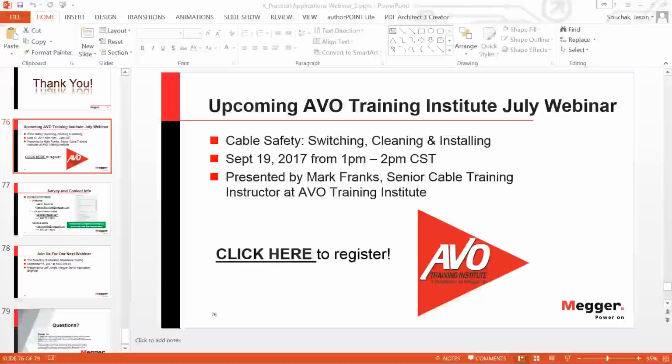I might just add, with relation to tan delta, if the tan delta test comes back good, it's a very, very sensitive test. So if it says your cable's good, the cable's probably good. But if your tan delta test comes back bad, it says your cable's in bad condition, I wouldn't necessarily blindly follow that. I would take a minute and ask, is there a splice that's maybe a problem? One of the few things that we can do relatively easily to address this is replace the terminations. You know, clean them up or replace them. It could just be as easy as dust over the terminations and you're leaking current over that.